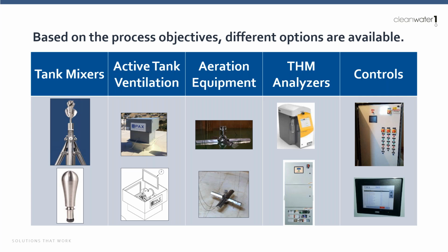also come with trihalomethane analyzers. So for larger systems, it can be appropriate to integrate a THM analyzer, implement some active feedback control, and turn off these aerators when you don't need the treatment. I'll give you an example of that in a minute.